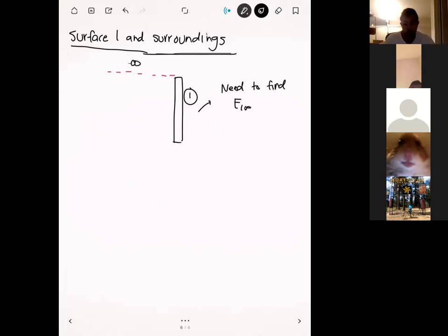All right, and so we can find this view factor a couple different ways, okay? One way is that if we assume that the opening to the surroundings is just another plate, it's not technically a solid plate because it's just empty space, but in terms of radiation, we have the radiation that's crossing that planar opening, okay?